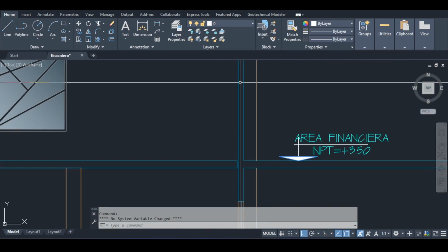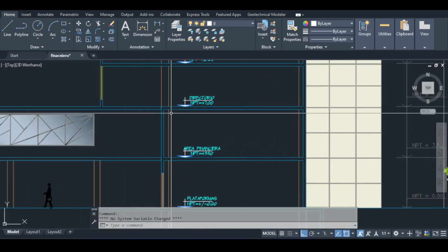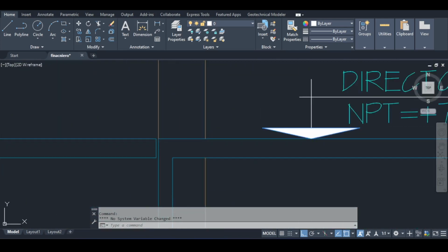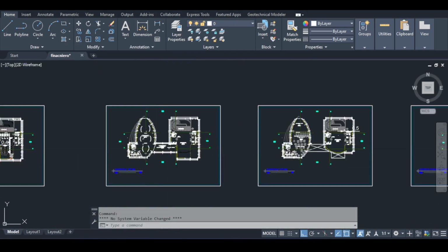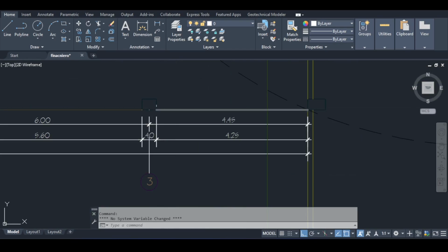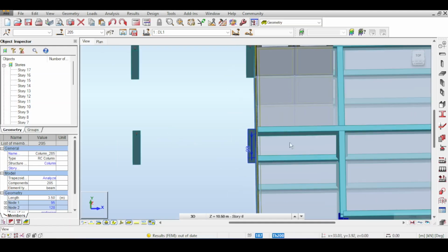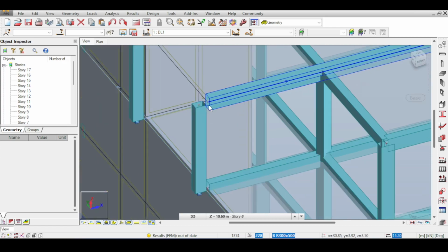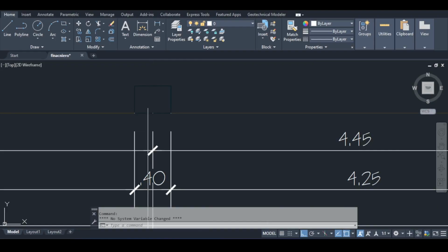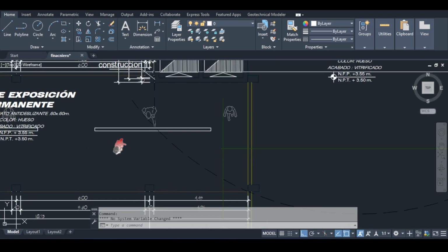Yeah, see? He's saying here, that's odd. He's saying this is my construction joint, but that doesn't make any sense because the building clearly extends beyond it. Give me a second, I need to grasp that. So I think I need a column here. I think I need another column here for the construction joint. So there's of course a construction joint here. Is there space for a column? Is there even space for it? No, there is no space for it.